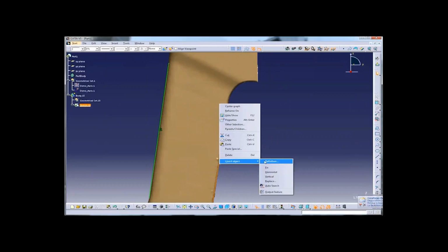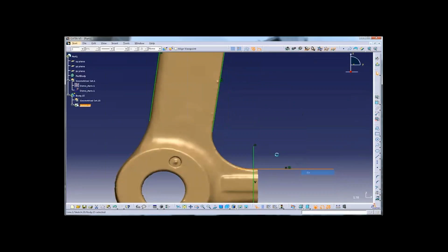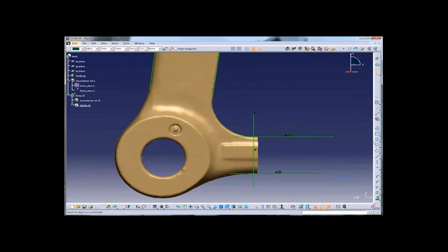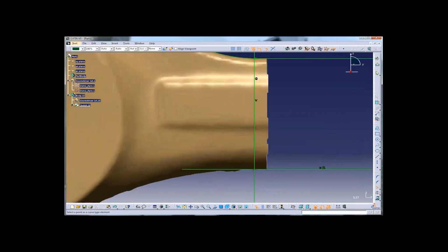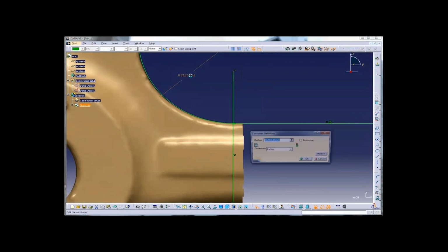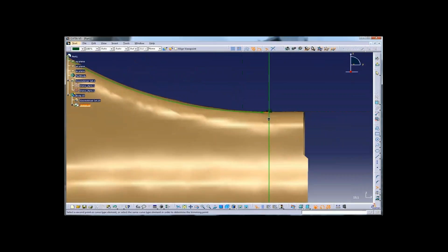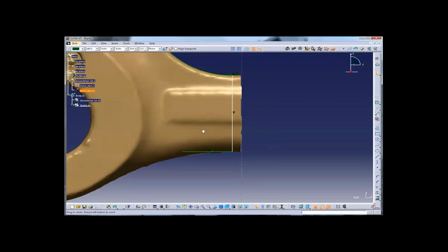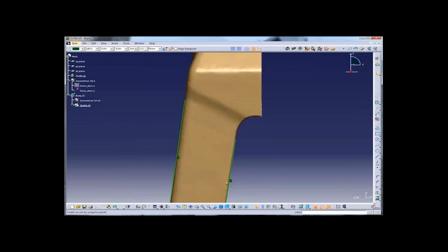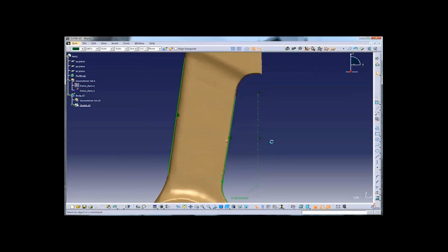When you create your first sketch, there are many different ways you can create sketches. Here I'm going to use the simpler way. I basically simply create profiles, creating them visually over my mesh boundaries. As I'm doing so, I can edit the dimensions so I can get a full parametric model, and of course create different constraints, like if you were designing a brand new part.